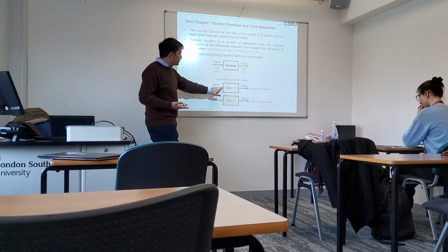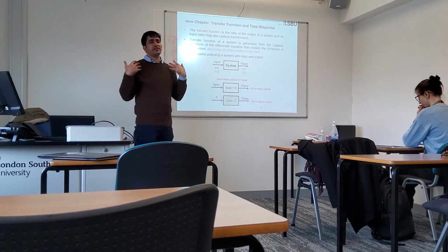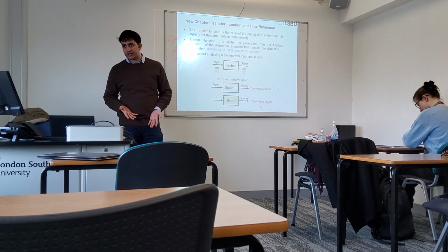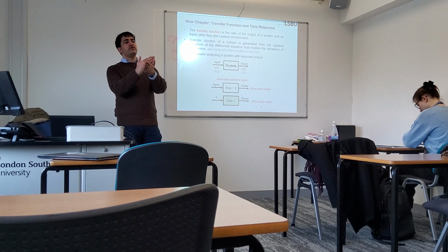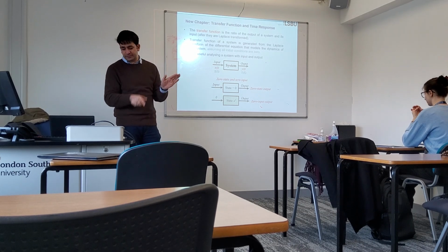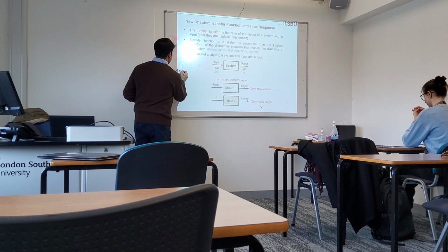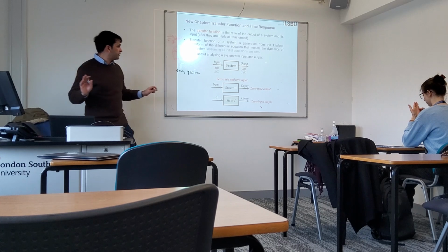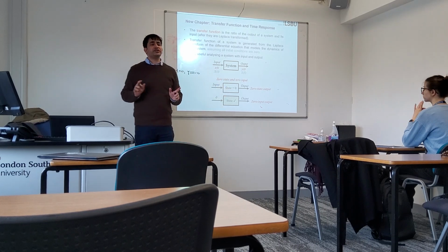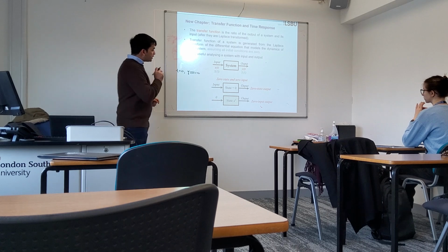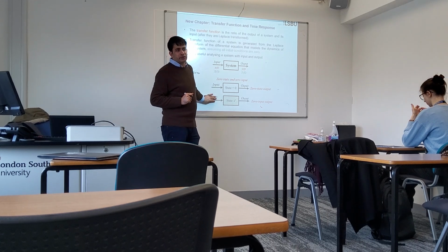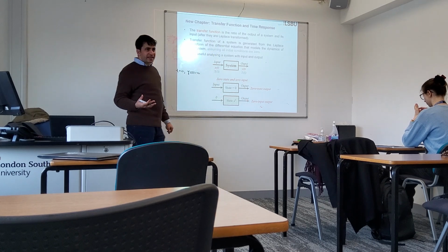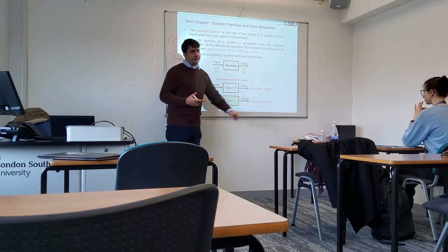In the first case, state is zero, meaning there is nothing in the system at the time when we started. At time t equals 0, there was nothing stored in the system. So it means that at time t equals 0, the output of the system was 0. So this is called zero state response. Now the second thing is when the input is 0, and at that point whatever we get would be the zero input response.